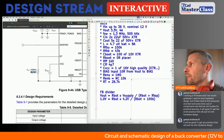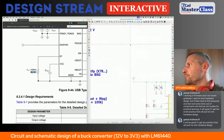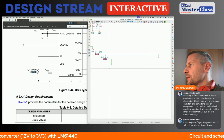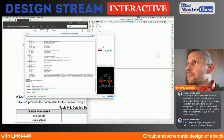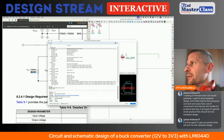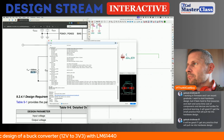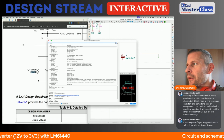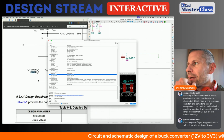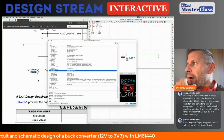Output capacitor, we set that the output capacitor will be 5 pieces of 22, quite a lot. So 22. And because I didn't use 22 at the input, I can choose anything like smaller output voltage. This is 1210, like big package. This one is my favorite, but it's not in the high quality material.